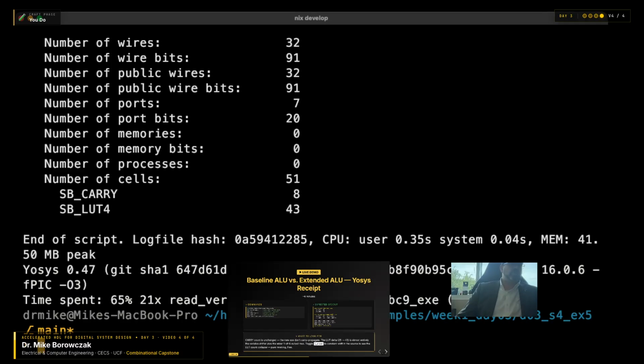And we notice roughly doubling, not exactly, but 43 LUTs required. No change to the carry. We didn't change those. So essentially the addition of our barrel shift as well as that XOR roughly doubled the cost. Not exactly, but added at least just about 20 LUTs just for those 2 operations. So the question is, how much did that barrel shifter really add?